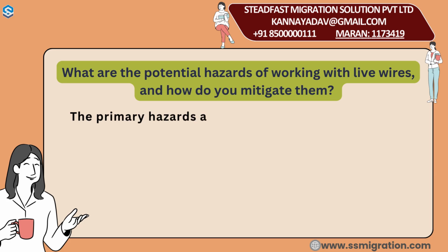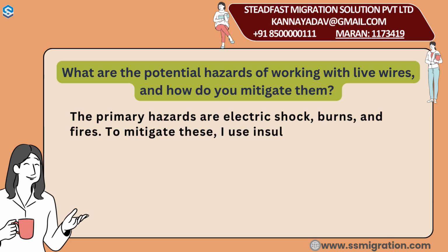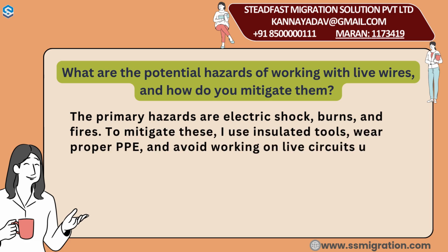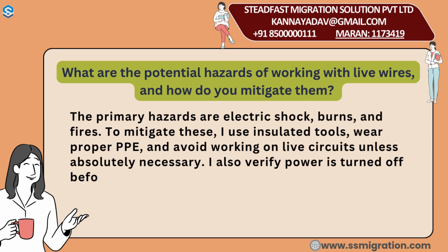The primary hazards are electric shock, burns, and fires. To mitigate these, I use insulated tools, wear proper PPE, and avoid working on live circuits unless absolutely necessary. I also verify power is turned off before beginning any work.